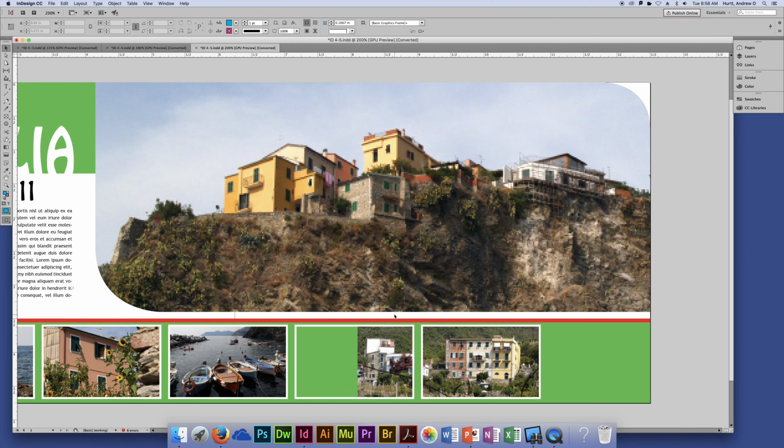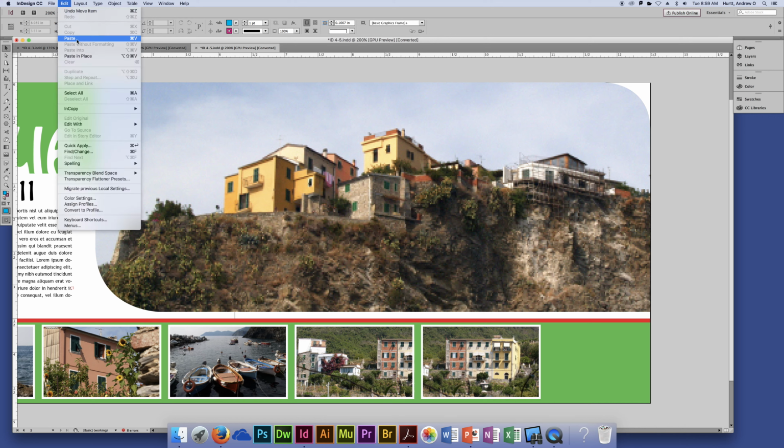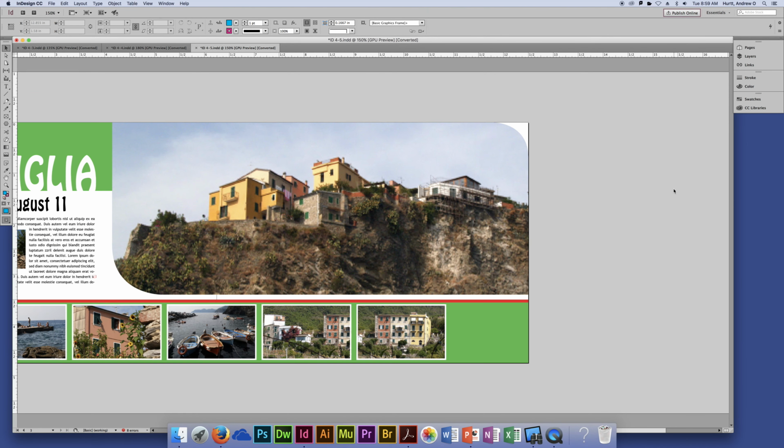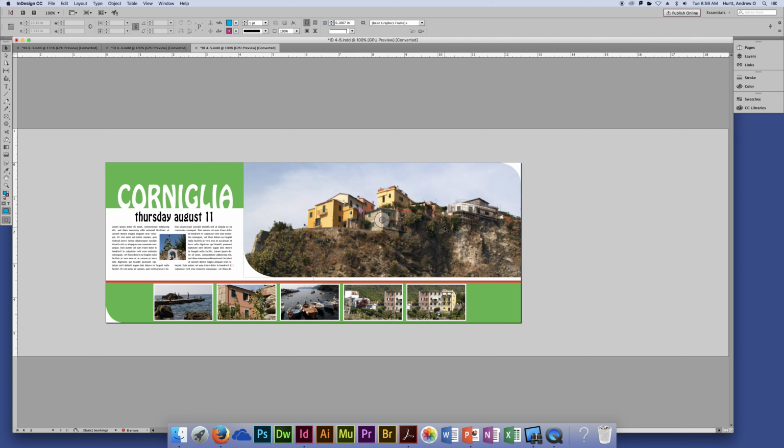That frame's a little bit different, but you'll see. There we go. And then you can adjust from there. The difference with just straight up pasting versus pasting into: you select the frame rather than the object, and you do an edit. Now it's not going to allow it because it's already there, but paste into or paste into place, and it'll keep it about the same shape. So you can copy and paste from frame to frame just by using the edit and paste into command.